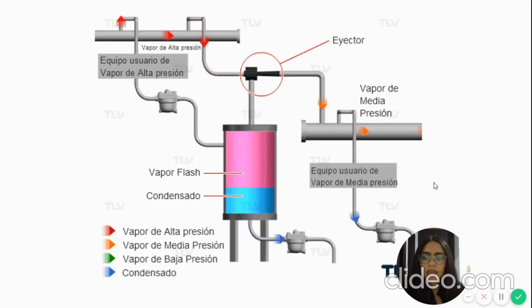To avoid this, a steam ejector is used that uses thermocompression to mix the flows of two different pressures, delivering steam at a medium pressure between those of the inlet flows to the ejector. This is what makes it possible to raise the flash steam pressure to usable levels.